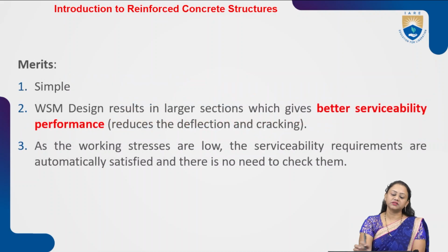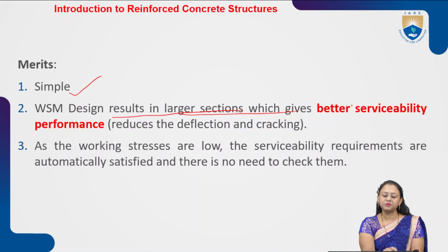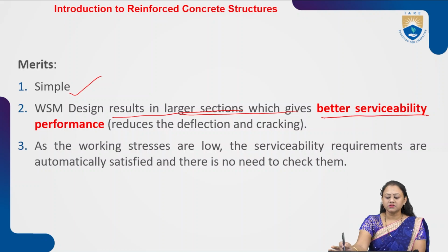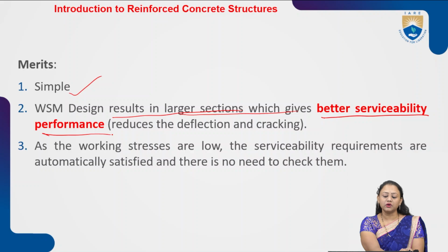Coming to the merits. It is one of the simplest methods, and it results in larger sections, which give better serviceability and performance. As working stresses are low, serviceability requirements are automatically satisfied and there is no need to check them. So these are the merits of the working stress method.